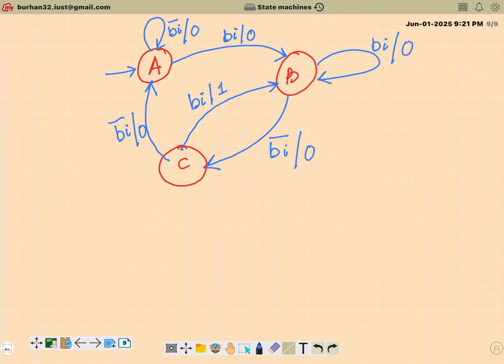And within a particular case, you will have 2 if statements. Fine, because this is a Mealy machine. And in a particular state, the output is not implied. You have to be very explicit. You have to mention the condition: what will be the output.